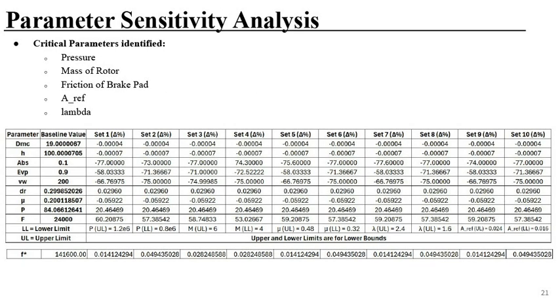From the parameter sensitivity analysis, we have found that the following parameters are critical for the system. Firstly, the mass of the rotor has been varied by 20%. The reason for choosing this is that it's related to the weight and inertia of the rotating components, which directly affect vehicle efficiency and handling. Brake pad friction, which is the friction between the brake pad and the rotor, μb, is the primary determinant of braking force output.